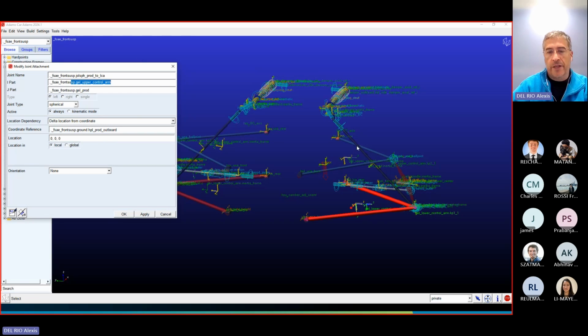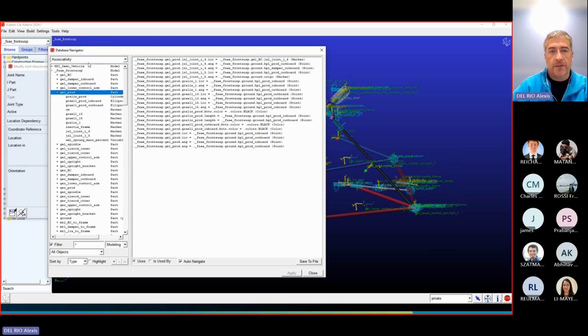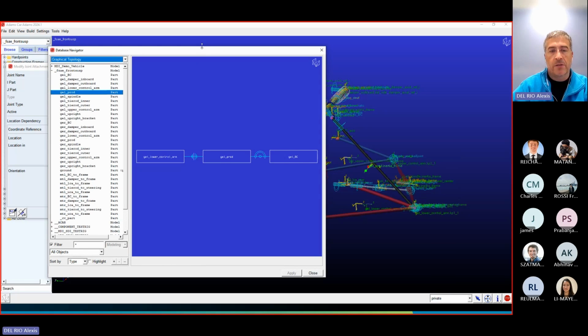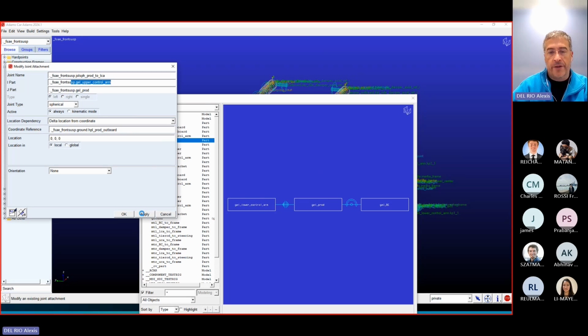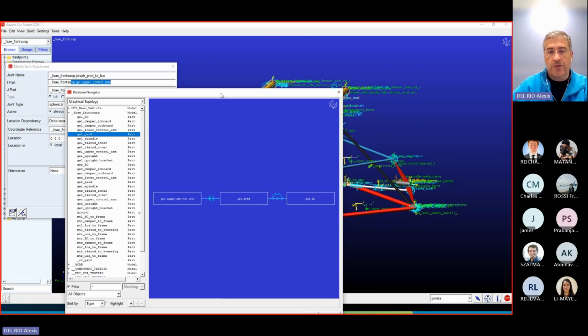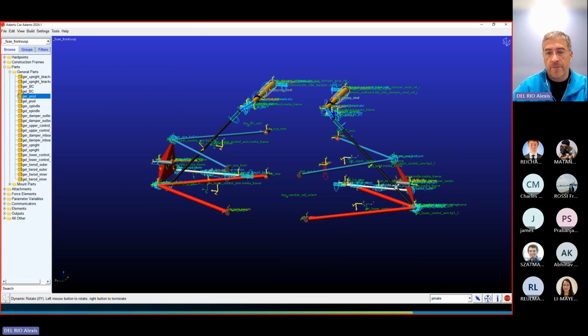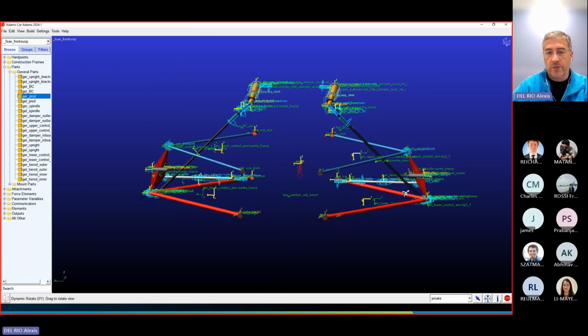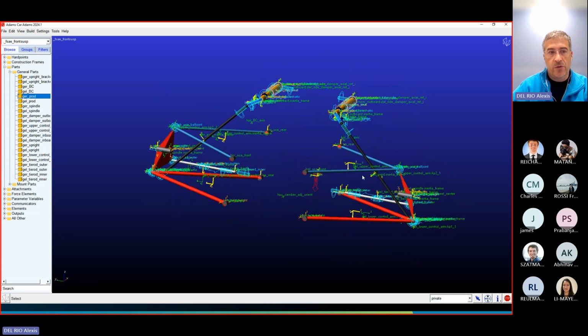And when we go again into the graphical topology, still the lower control arm, and then the upper control arm. So now it's done. So now you got it connected to the right thing, except that the position is not really the best one. So then what you want to do is to change the hard points. You want to investigate what hard points they are related to.